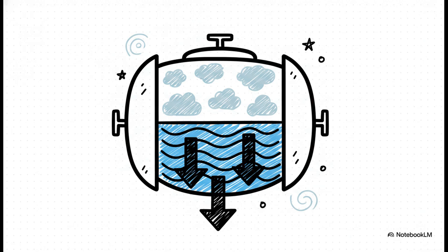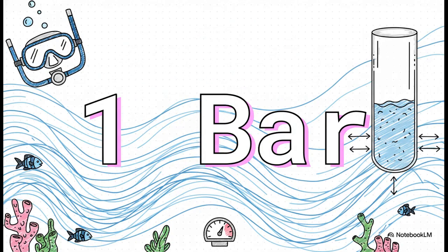And this actually brings us to our first major engineering challenge. You see, the pressure at the bottom isn't just the ambient gas pressure of the system. It actually carries the physical, literal weight of all the liquid pushing down on it from above. In the industry, we call this static pressure. Think about it like scuba diving. When you dive into the ocean, the deeper you go, the more pressure you feel in your ears, right? Water is incredibly heavy. In a plant vessel, if you have roughly 10 meters of liquid water pooling at the bottom, that static weight adds roughly one entire bar of pressure to the bottom reading compared to what you'd read at the top.